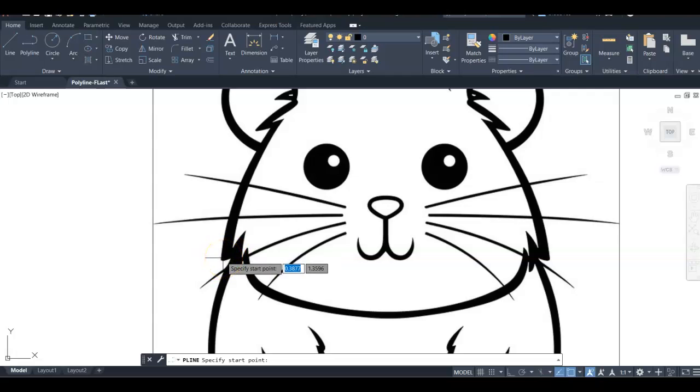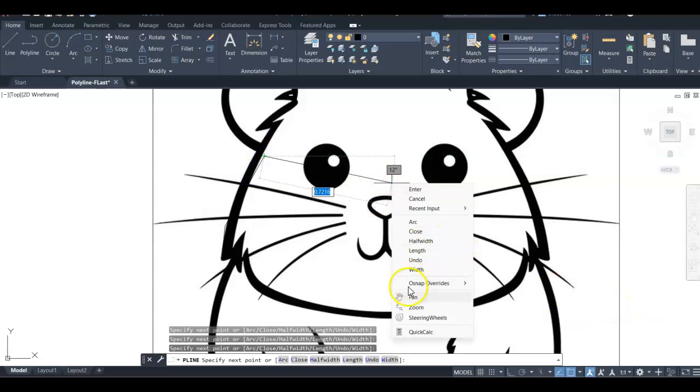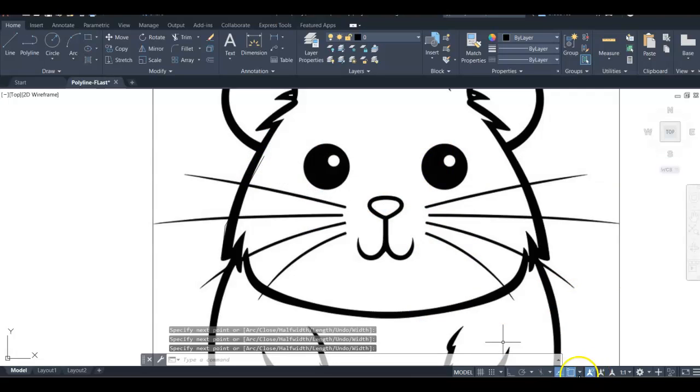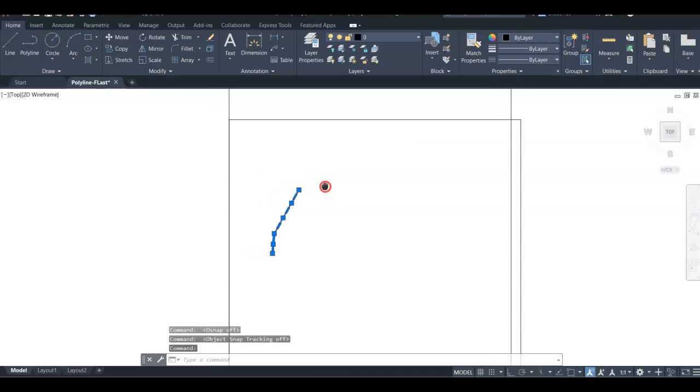Now, a polyline allows me to just kind of draw certain lines. The more you click on this, all we're doing is following along different paths. As you go through, let me enter and cancel this, you're probably going to want to have your snaps turned off. And if you've got your object snap tracking, object snaps, or your grid mode turned on, those are going to give you some problems here. So turn those off.